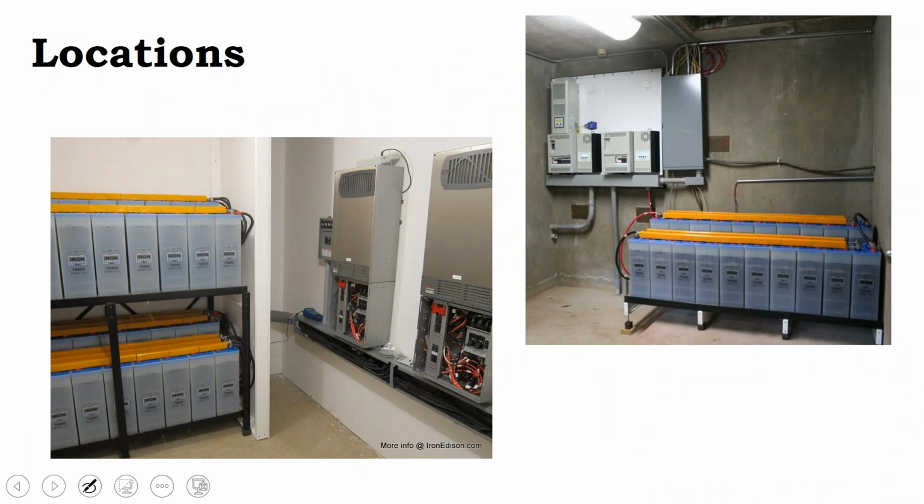So let's take a look at some of these pictures. Are these rooms code compliant? Well, if you actually have to take a hydrometer and stick in a stick and measure the specific gravity of that nickel cadmium battery, that working space is not accessible. You need 3.5 feet of working space there.